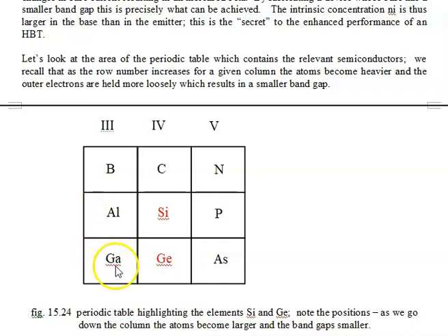So we replace a little bit of the gallium, partially of the gallium, maybe 30%, 40%, 50%, depending on the kind of device we want to make, replace the gallium or part of it with aluminum. Aluminum is higher up in the periodic table. It's lighter, and it has a higher band gap than gallium. Gallium arsenide has a band gap of about 1.45.